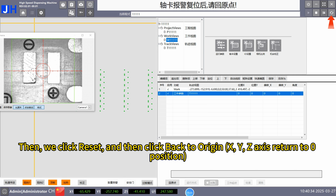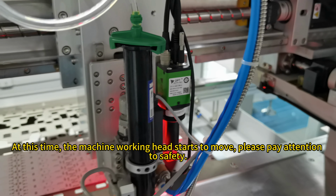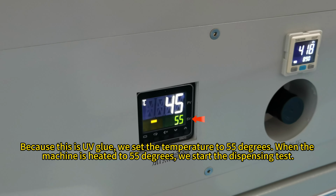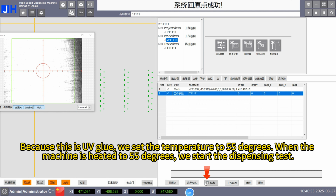Then, we click Reset, and then click back to Origin X, Y. Z-axis returns to 0 position. At this time, the machine working head starts to move. Please pay attention to safety. Because this is UV glue, we set the temperature to 55 degrees. When the machine is heated to 55 degrees, we start the dispensing test.